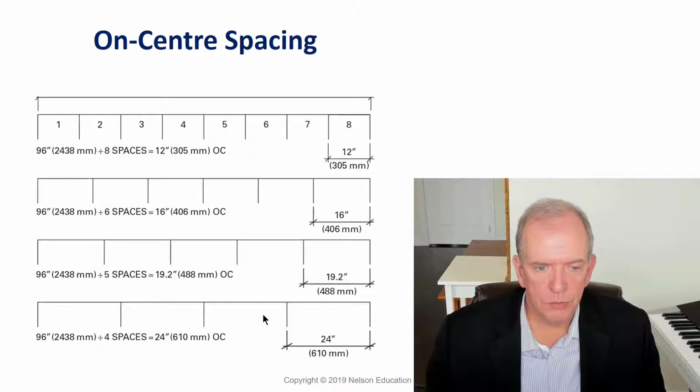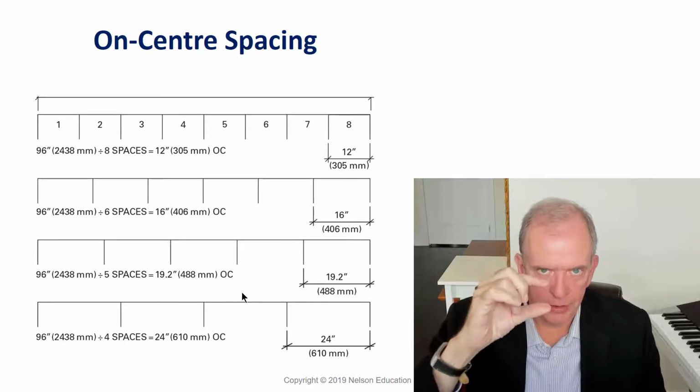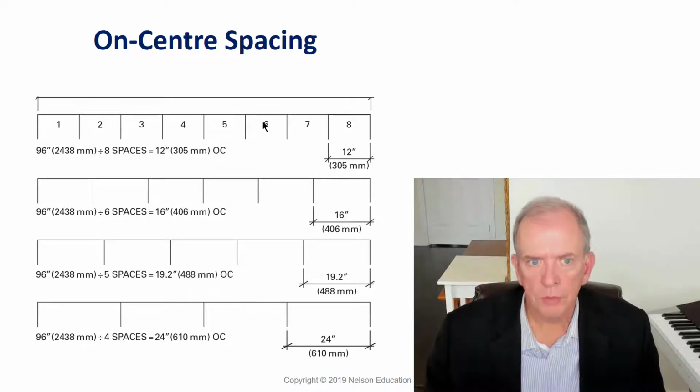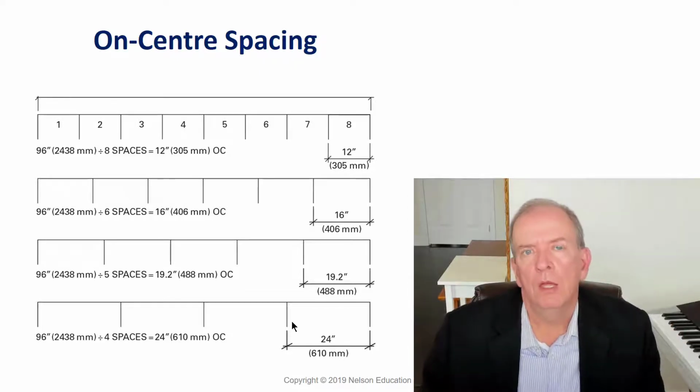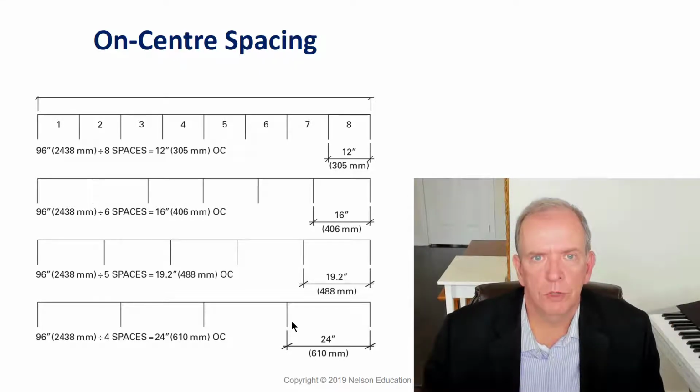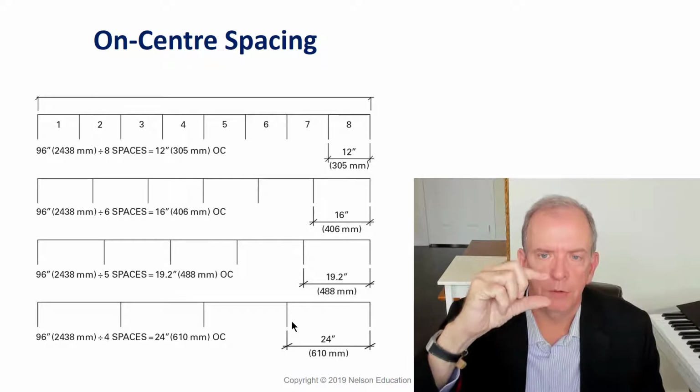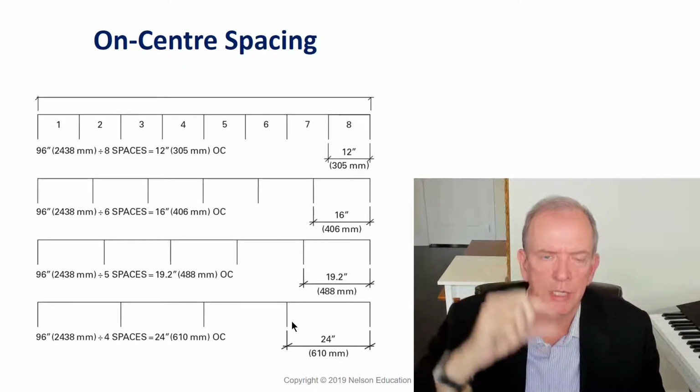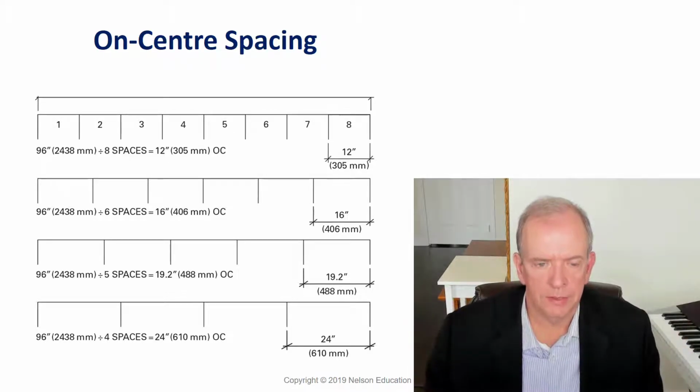Obviously, this would be a little bit of a problem going 24 inches with a subfloor. We would have to have a dramatically thicker subfloor than we would here because of the deflection rates. I have seen as much as 32 inches on a span, using engineered joists, for a prefab condominium building that was being built. I think it was Mattamy Homes, and they had a special engineered subfloor, about 1 3/8 inches thick, that would span that distance.